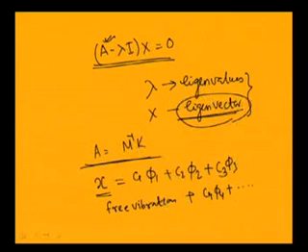So, in this way you can analyze or find the free vibration of a system by using this normal mode method. Similar to the 2 degrees of freedom system, first you should find the A matrix. A is nothing but M inverse K. First find M inverse K, that is A. So, A equal to M inverse K.